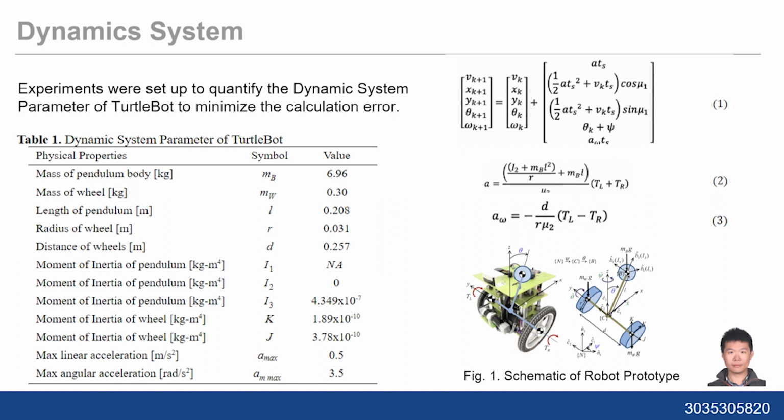Since the ROS system of the Turtlebot can support linear and angular velocity input, we only use TL and TR in the MPC computation and deliver the optimal velocities to the Turtlebot after open loop prediction.